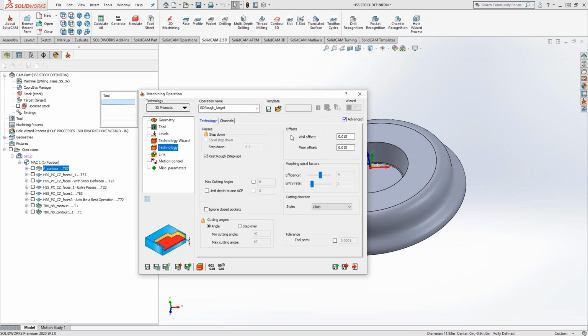Now, with 3D iMachining, we actually did this at Toyota. They were making wax molds, and it was a fully 3D part, so it wasn't a prismatic part. So what we were able to do is leave it on general, and switch our scallop to be a very small scallop inside there to get a decent finish. And we were actually able to get a finish that met their requirements using just 3D iMachining by itself.